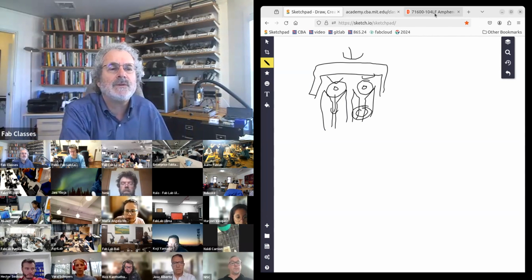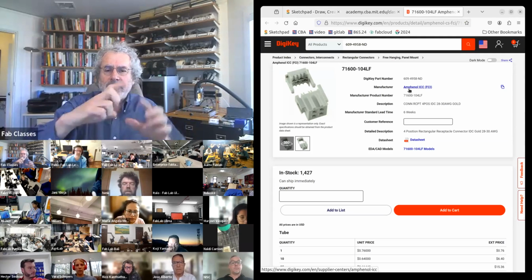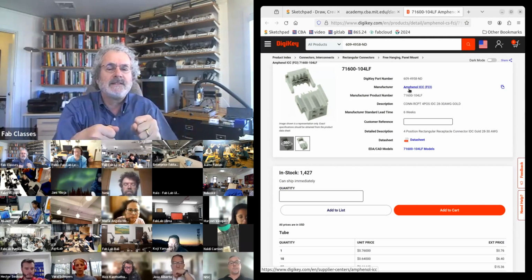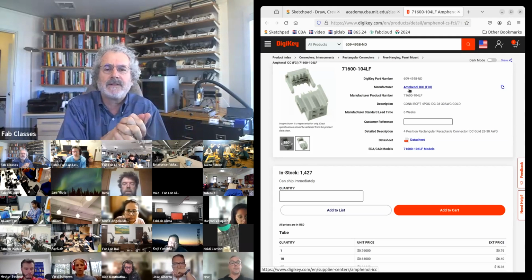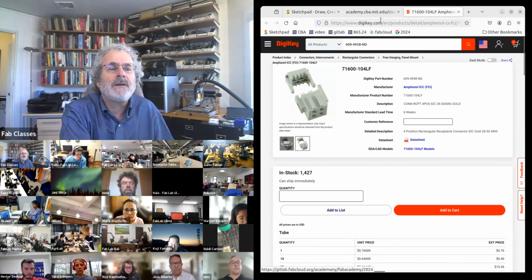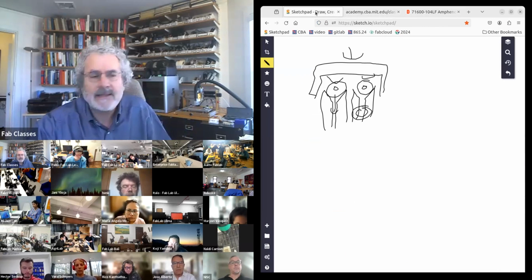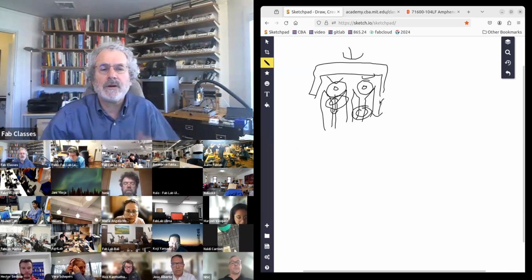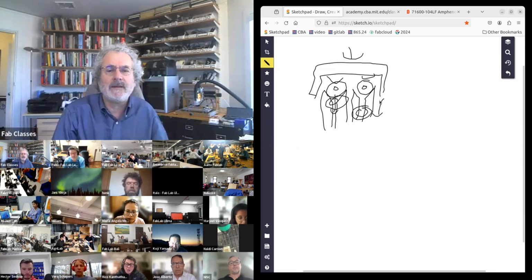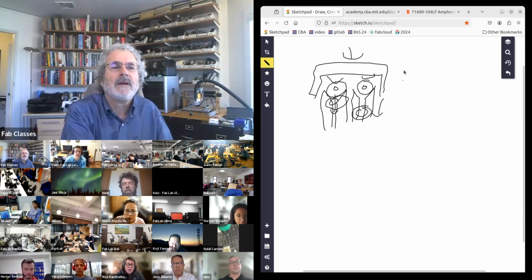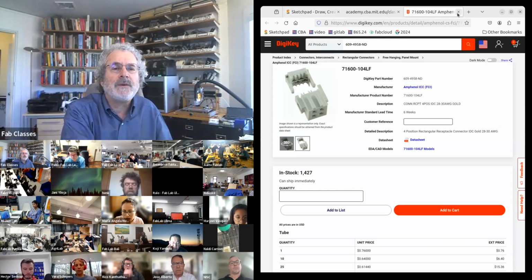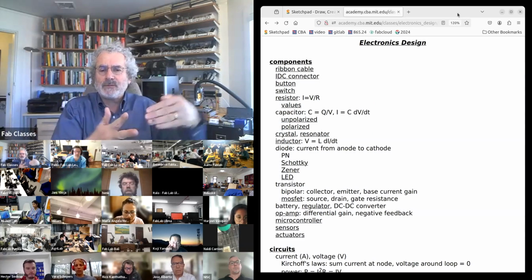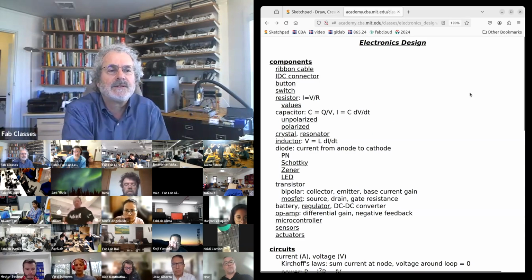What it lets you do is slide the ribbon cable in, squeeze it down with a vise, and then make contact to make the connectors. The one note is if you only squeeze it down a little bit, the connection isn't reliable. You need to make sure the wire gets pushed all the way in, and then it makes a good connection. So that's what we use to go from ribbon cable to a connector to make multiple connections.